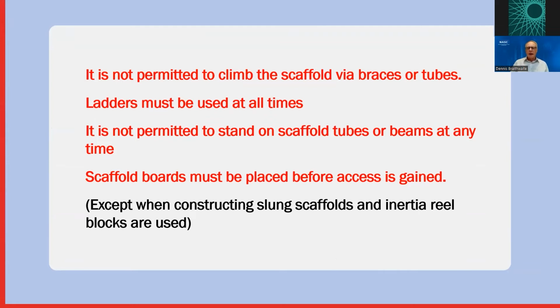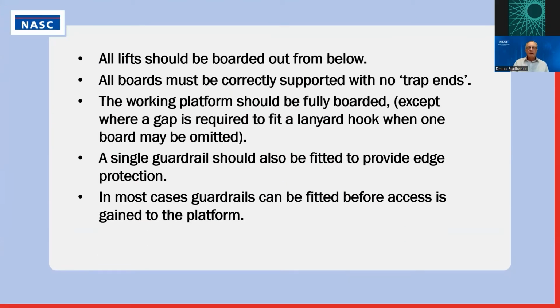There's one exception to that, and that's when erecting slung scaffolds, where it's not actually possible to fit the boards before you've actually fitted the structure. So that's by use of inertia reel blocks, basically. It's quite a difficult job, which if you've been involved, I'm sure you understand. All lifts need to be boarded out from below, so that there's a platform ready to stand on when you get up to that level.